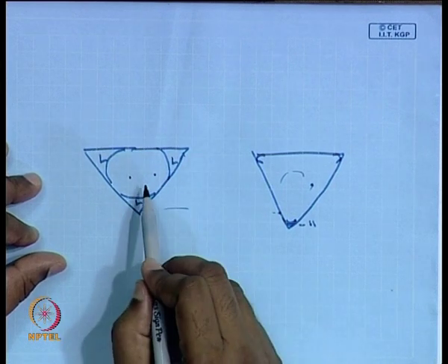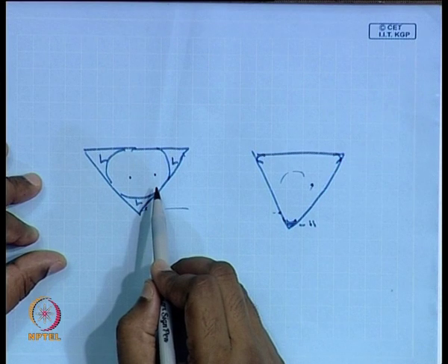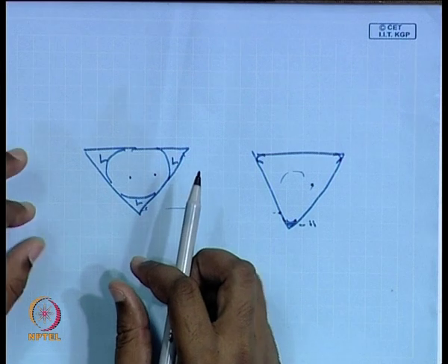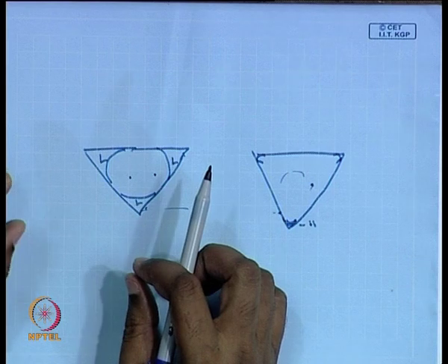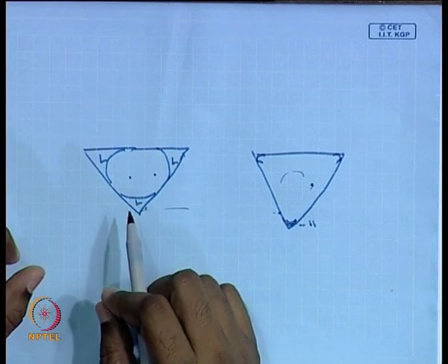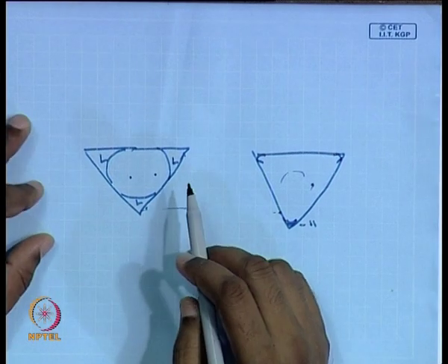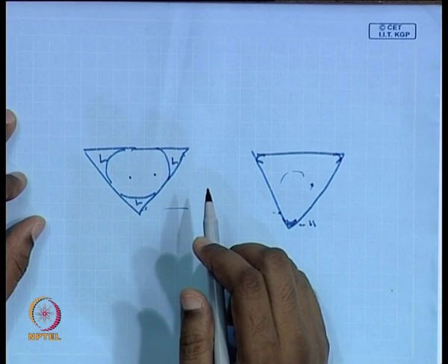And this is another limitation which can happen in the case of heat pipes, especially micro heat pipes, as dimensions become smaller and smaller and the vapor core available would be very small. One also would have to think about what would happen if I tilt a micro heat pipe, if I have a body force which is acting against a heat pipe.